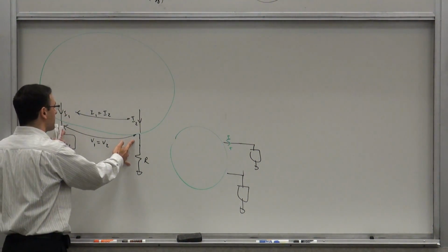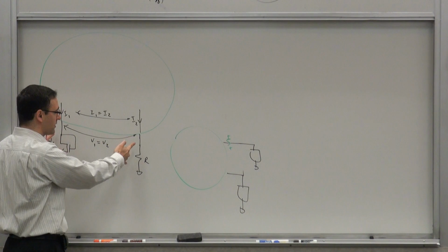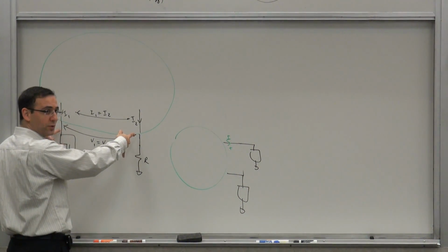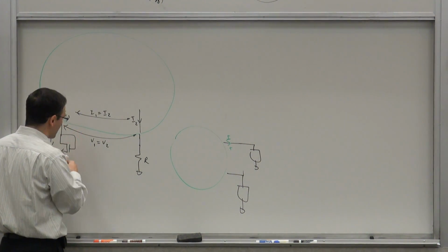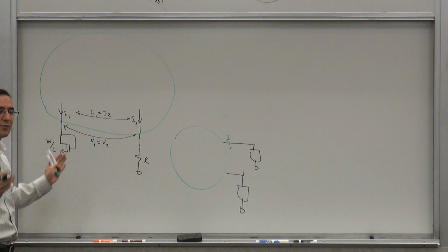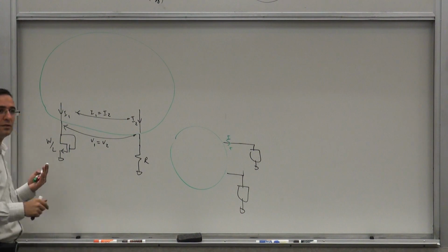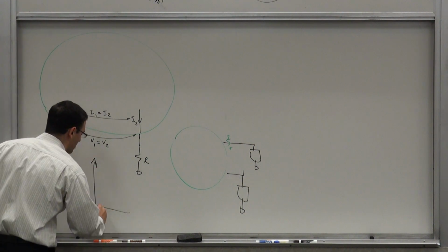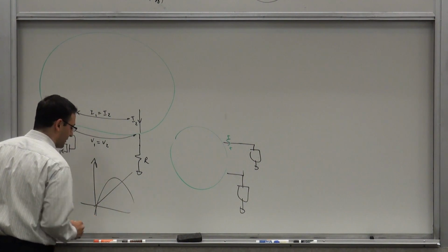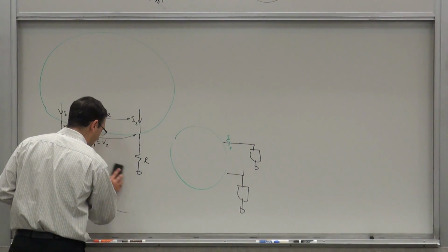If you choose these two currents, whatever value you could choose for this resistor, and you can think about this as a different resistor, I can put the same voltage on them, right? And basically, a resistor doesn't perfectly work actually because you have to have some nonlinearity, something that allows them to cross. So if it's a nonlinear element like this one, this allows it basically to find a solution. And sometimes there's more than one solution because of nonlinearity. For instance, you're basically trying to cross two curves, one which is like this, the other one which may be like this. And you have two or multiple solutions in general in a nonlinear system. You will see how it works.